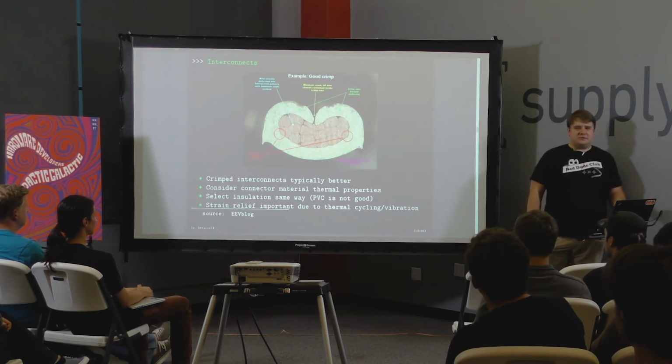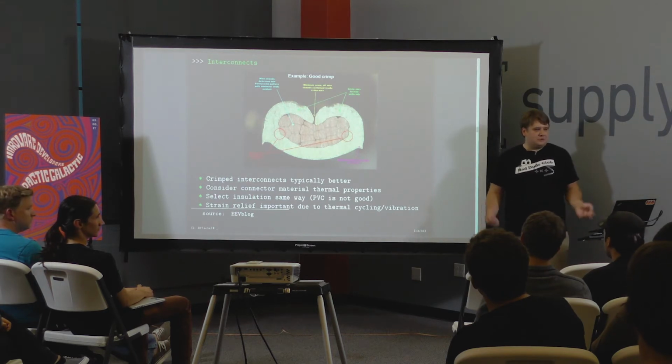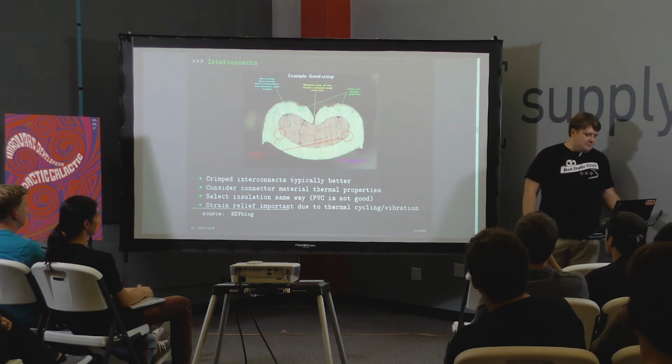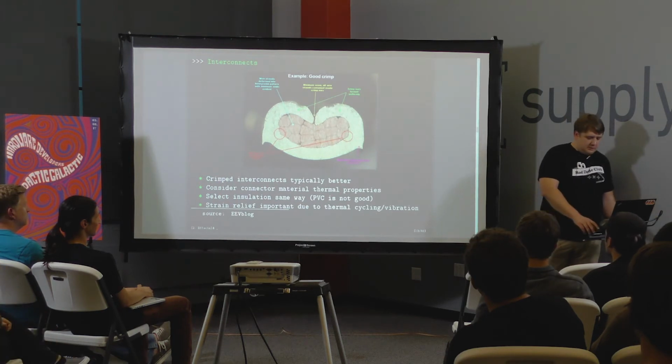And then strain relief, because you're going through turbulence, stuff's shaking. That's probably why some of your wires came loose, because when you're moving, things come out. But if you have stuff stationary, that's all good. But I guarantee you the thing's gonna be vibrating, so you gotta deal with that.